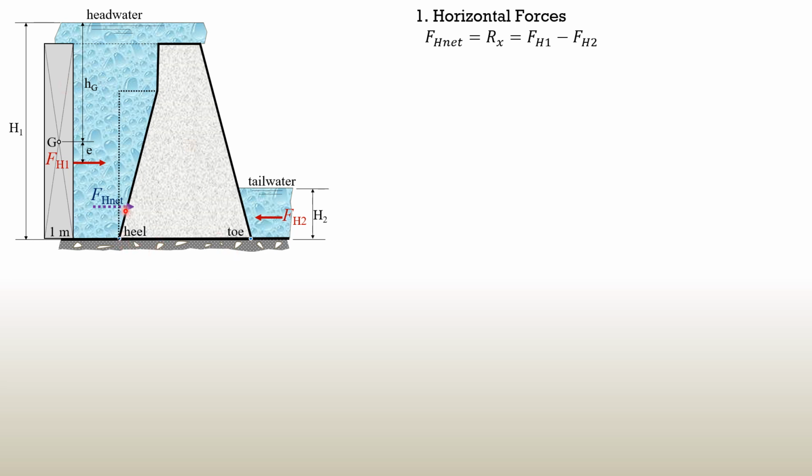Next, we consider vertical forces. We draw lines from the end of this point on the heel up to this level, because we have a varying curve, a varying surface, on the face. Then we have another volume to be considered, this volume here and this volume here. The same is true with the volume of masonry as shown, and this one. We will call this weight 1, and from the previous principle, weight 1 is simply the weight of this triangular wedge of water. Weight 2 is the weight of this rectangular wedge of water, and of course these weights pass through the centroid of the volume considered.